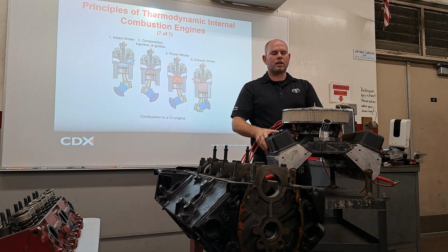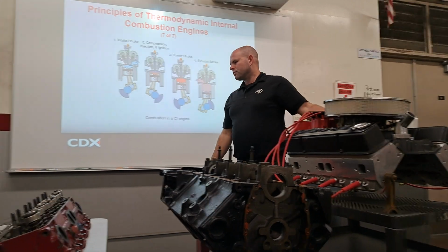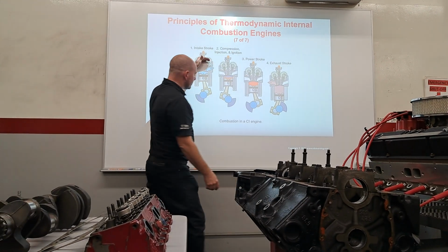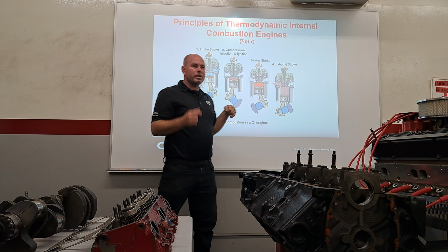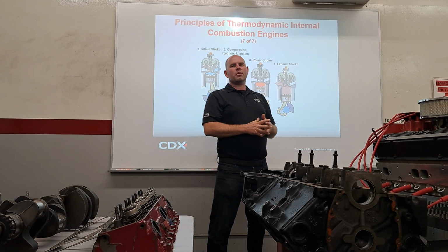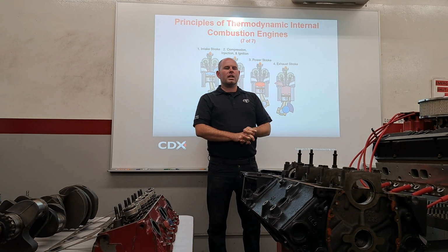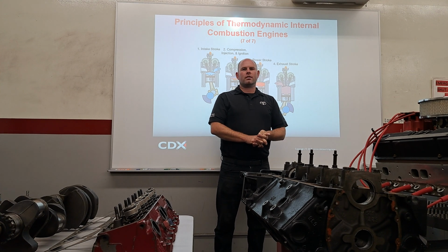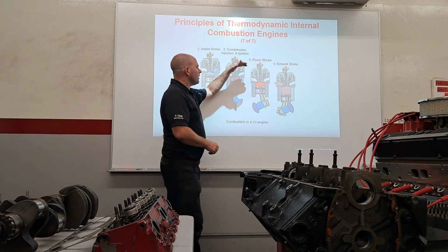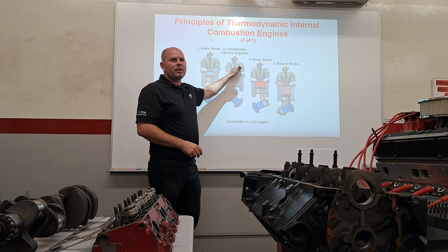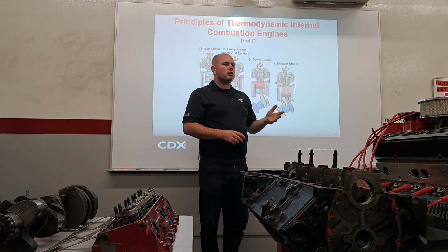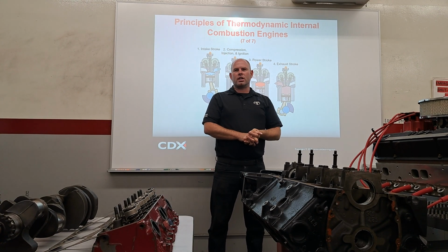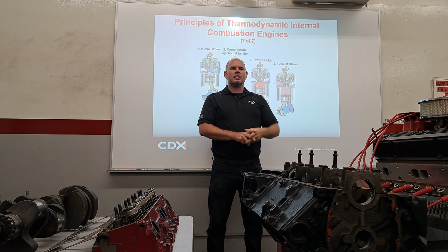Diesel's way different. The diesel pulls in just air. There's no fuel in there because diesels don't have carburetors. They can't have carburetors. A diesel with a carburetor wouldn't work. Diesels have to have fuel injection, but not only that. You remember how GDI is a thing, right? Direct injection gasoline engines. Diesel's been like that for like forever.